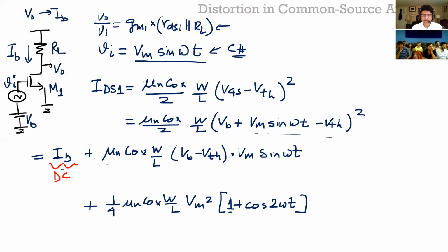Now, once you give a signal, you get this linear term, and if you recognize this term, this is nothing but what you calculated GM as. So this is 2IB. If you just take the algebra and reshuffle it, you'll see that this is 2IB over V effective, and V effective is this term here, if you remember, right? And then the linear term.